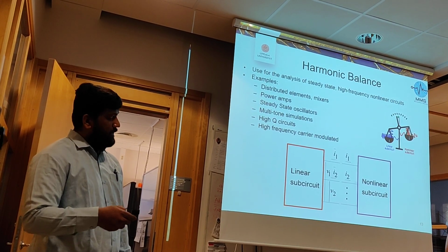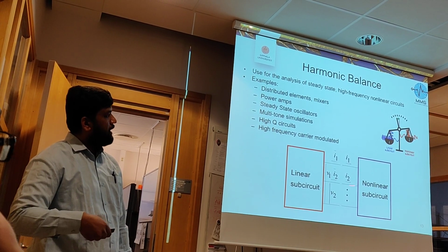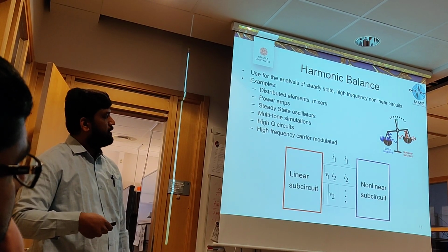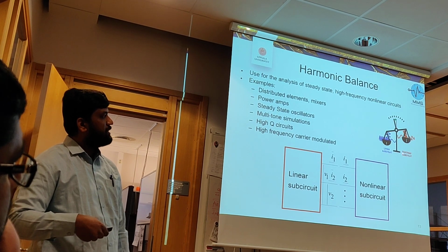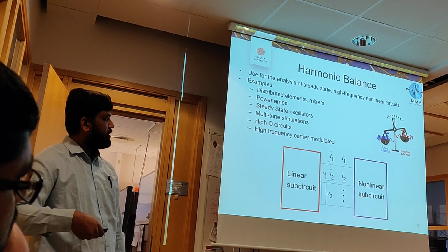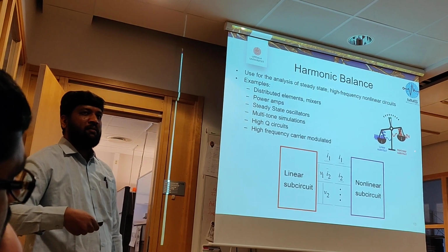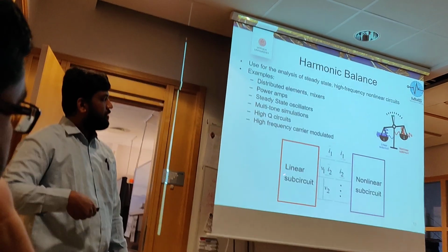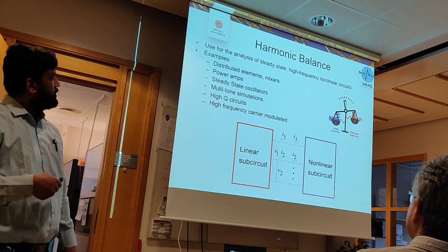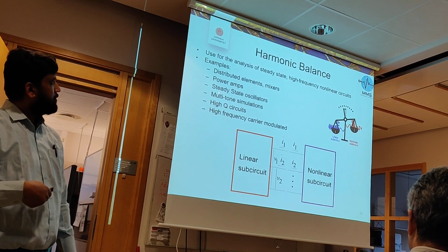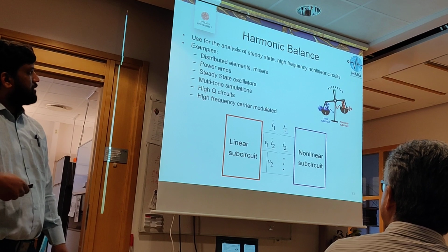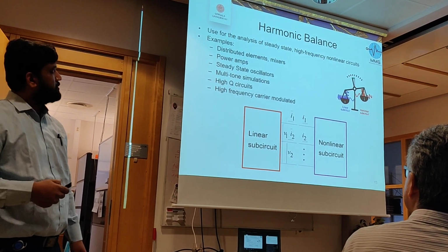And this is harmonic balance. This is made especially for non-linear circuits. You see that one simple picture is saying that you should balance linear and non-linear circuits. Suppose in linear circuits you have RLC in your circuit and you have non-linear characteristics with some transistor and so on. They should interact every time and the calculation should be performed properly. So devices like mixer, power amplifier, oscillator, multi-tone simulator, IQ circuits, and high frequency carrier modulator go with harmonic balance.